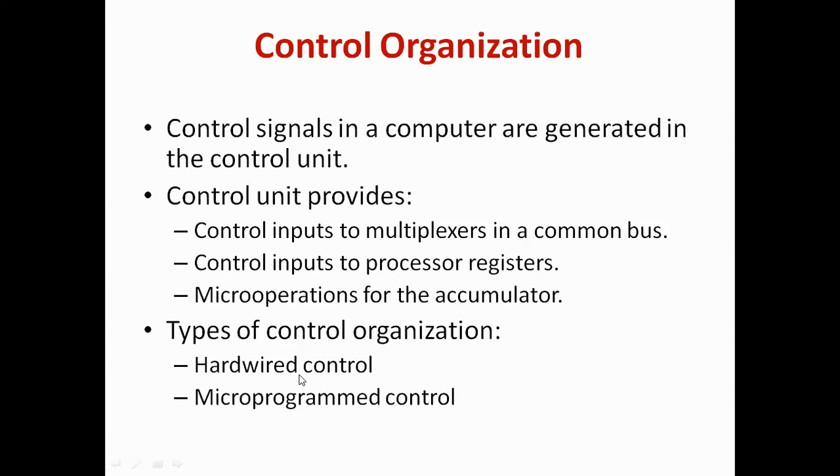Obviously, the advantage of this unit will be that it will be fast, because there is no code to be executed for controlling. Hardware is doing the things, so it will be a fast unit. And the disadvantage will be that it is not flexible. We cannot change this. If we want to add some more control signals or change some control signals, we need to do hardware changes, which obviously are difficult.